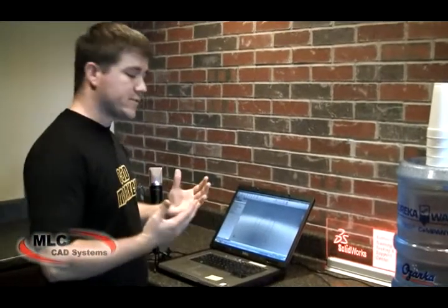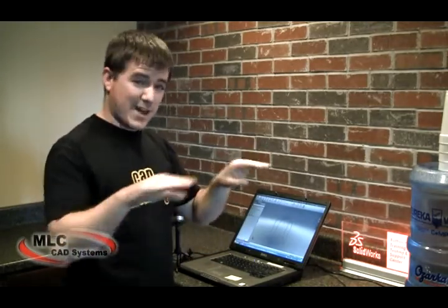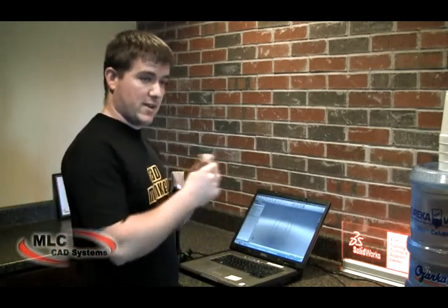Okay, so you notice that I've been doing a lot of 3D sketching. I'm using as many relations as possible, trying to cut down on the number of dimensions. If you have multiple dimensions that are really driving the same thing, you're causing yourself problems, giving yourself more work to do, plus you're going to have these things fighting each other, and really that's not your design intent. On a luggage cart like this, it's always going to be the same height on all four legs. So you want to set those equal to each other, or set the tops of them even, some way to maintain the design intent and cut out the amount of time you're going to have to spend changing dimensions and trying to get everything to line up.